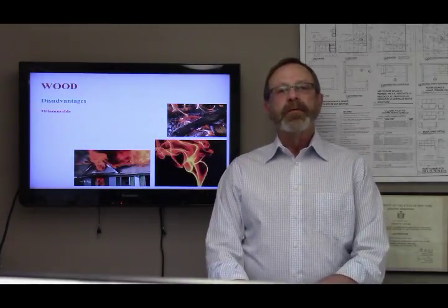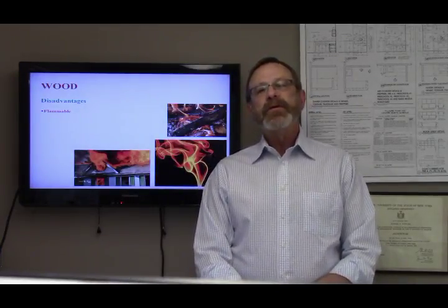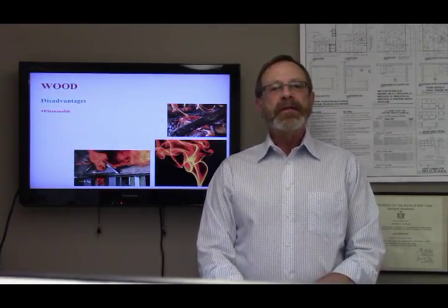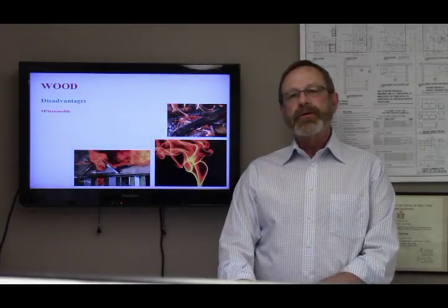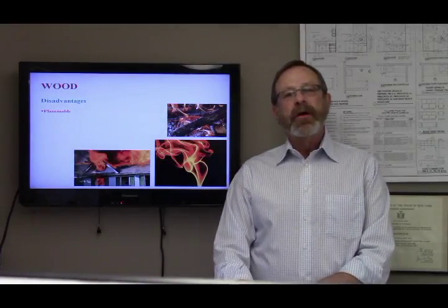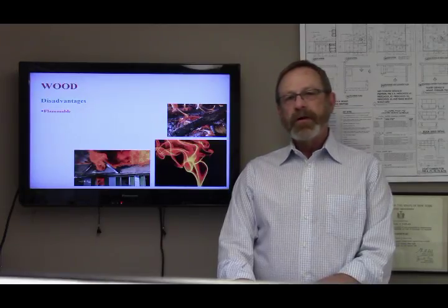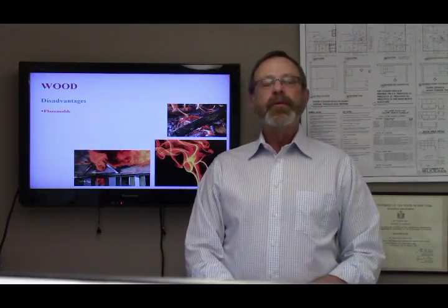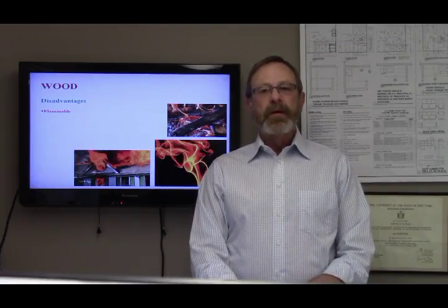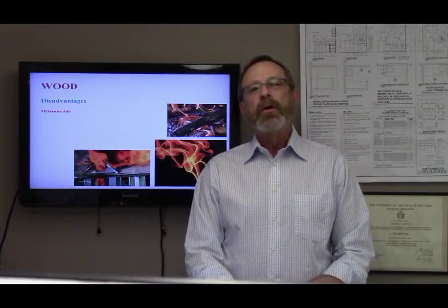All woods are flammable, but the rate of burning depends on moisture and resin content. Wood species are graded by the flame spread index, a measure of the distance spread on a flat wood surface under standard conditions, and the room corner test, which simulates full-scale conditions of a house fire. Flame retarding treatments reduce the rate of wood burning by a factor of up to 2, but do not prevent it. Because of these complexities, wood and wood-derived products are all rated as highly flammable.